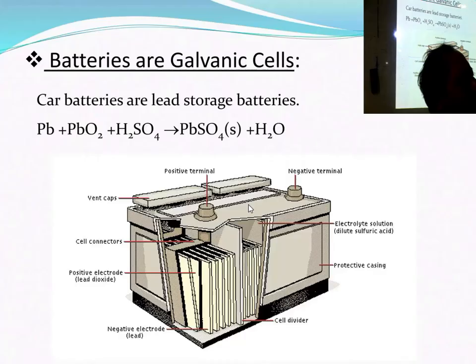Cathode, anode, with plastic separators in between. These are also perforated separators, so that the solution can pass through, but the plates do not come in contact. Plastics are a very good separator. Usually these are polythene plastics. Why is it good? Because it does not react with any acid. Plastic is good that way because our acids also come in plastic containers, polythene containers. That means plastic is acid proof.